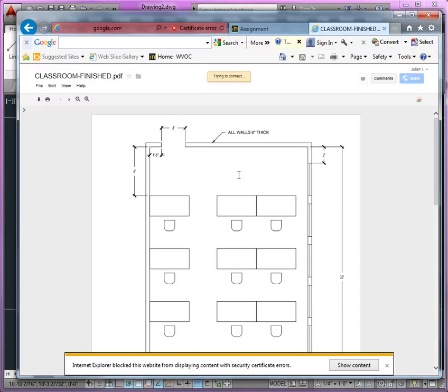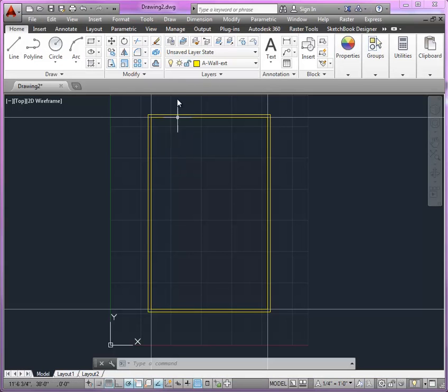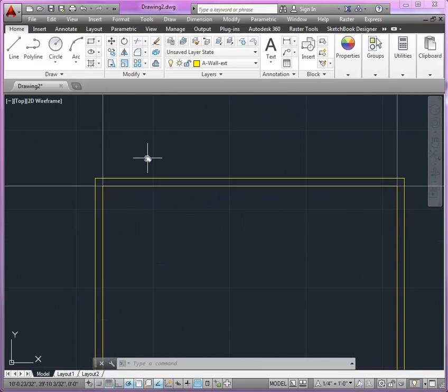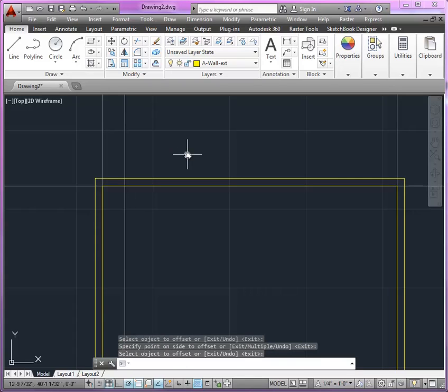Now, if I start up here in this area, you can see that we're 1 foot 6 inches from the corner, and we just have a very simple 3 foot opening, right? If I go tab like this, how am I going to specify that? Well, you can see here's where your construction lines already start working for you, right? If I use offset, I have 1 foot, 6 inches. Pay attention to the notation, right? Hit enter, select that construction line, and offset to the right. Hit enter again, you exit offset, hit enter one more time, and you're back in.